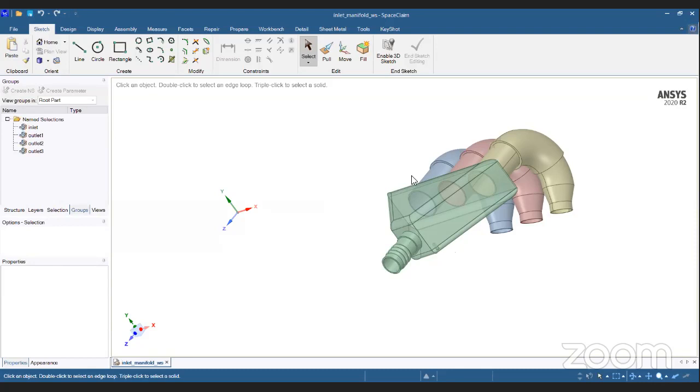So if, for example, you wanted to do an external flow problem, and this was a complete solid, and you build a cuboid around this geometry to represent the bounding box or the ambient conditions, then if the box is completely closed and this is a complete solid, then again, that would be a watertight geometry. So wherever the fluid flow domain is clearly defined without it leaking through gaps or holes or intersecting surfaces, that would qualify as watertight.